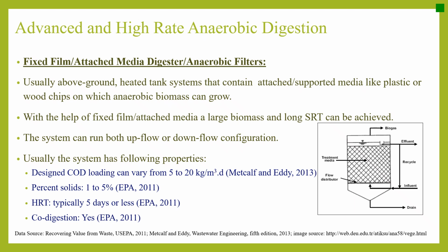Usually the system has the following properties. Design COD load can vary from 5 to 20 kg per meter cube per day, and recommended percent solids varies from 1 to 5%. HRT is typically 5 days or less, and yes, the system is suitable for co-digestion. And this is how one of the systems looks like.